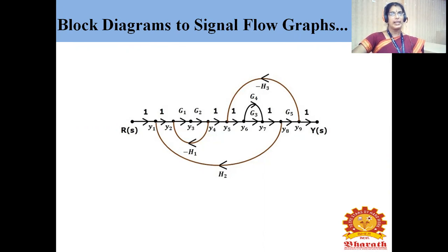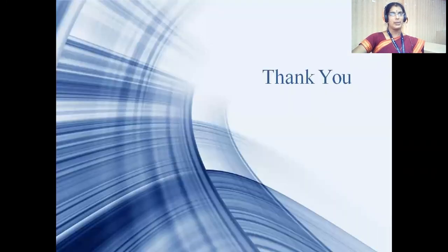If it is a complicated system, instead of going for the block diagram reduction technique, we can convert the block diagram into a signal flow graph and easily find the transfer function of the given system. Thank you.